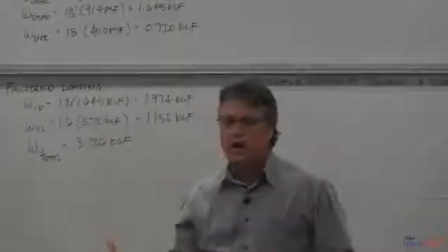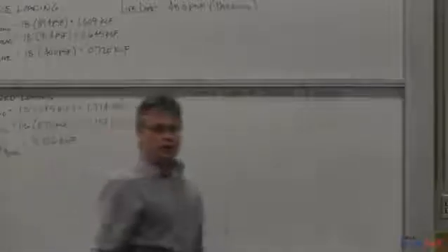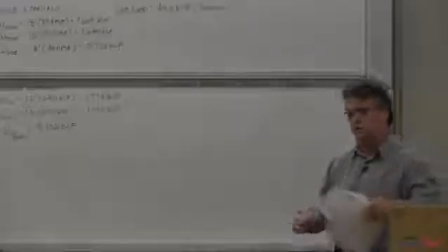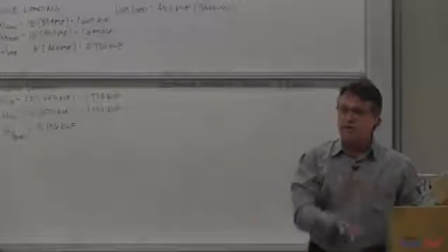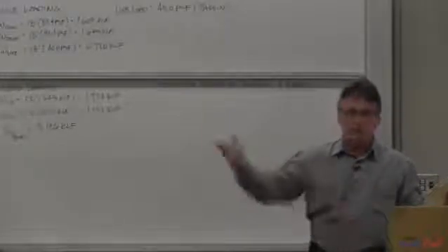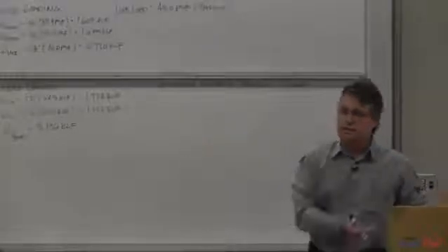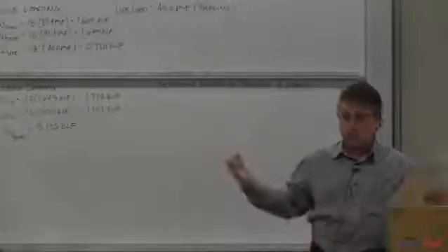Okay, I need to figure out how much pre-stressing steel I need. Which span should I start with? Which span do you think I should look at? The long one's going to control this, right? You guys did homework number 3. It was genius. You had a long span. It controlled. It's where the stresses were actually not working, and we played with the shorter span to make the longer span work, okay? Homework number 3 right now.